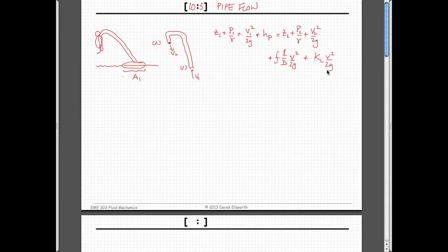Okay. So let's talk about the important components. Let's put some numbers on this. I don't know how tall the guy was, about 6 feet. Let's choose 2 meters. Let's talk only about the magnitude of minor losses. And for a right angle bend, it was of the order of 1, if you remember from what we did. Something like that.